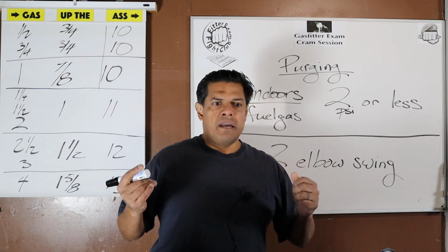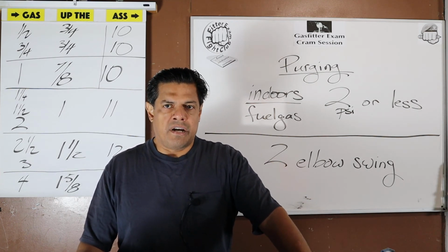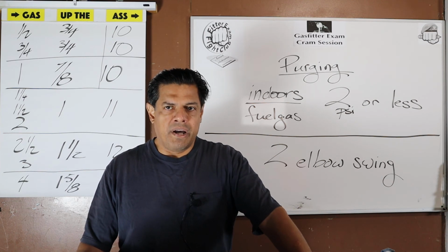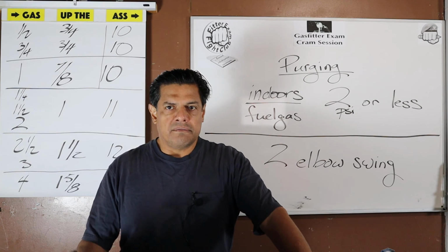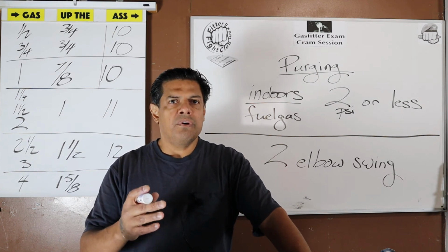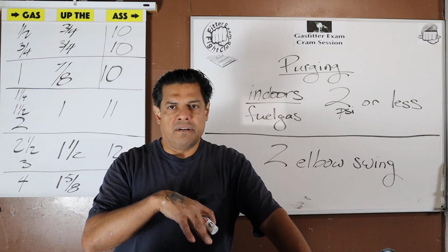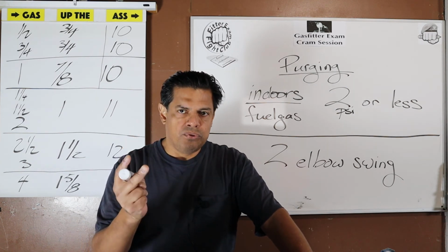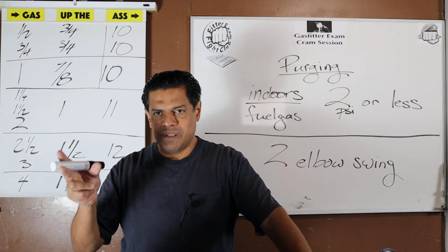I always feel that in a gas system, if you can do a job with 1 elbow instead of 2, then hey, if you can do a job with 1 fitting less, you've just saved yourself 2 joints. I see every joint as a potential leak.